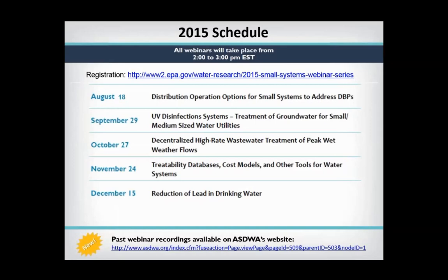Now, I do know some research has been done on one very large water system that tended to have too much alum carryover, and they actually started adding the orthophosphate at rapid mix to precipitate out some of the excess alum so that it didn't go out into the distribution system, and then they introduce phosphate again at a second point to trim the concentration. I don't think intrinsically it matters. There may be some specific operational engineering constraint at a given system that would dictate it better one place than another.